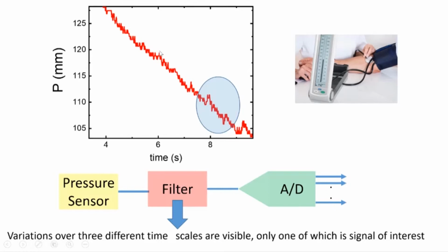All right, so what we are seeing is that, in order to interpret signals, what you may need to do is filter the signal, or remove certain frequency components and maybe enhance certain frequency components. When you want to do that electrically, you need a frequency sensitive element. Now, resistors are not frequency sensitive.